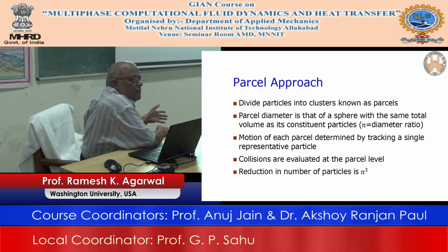Again, whether it is the Gidaspow drag law or some other drag law, use the same thing. The collision model is Hooke's model. Everything is the same, except you are saying I am not going to use very small little particles and just track them. I will make them bigger. That's all. The whole philosophy, the whole theory is the same.